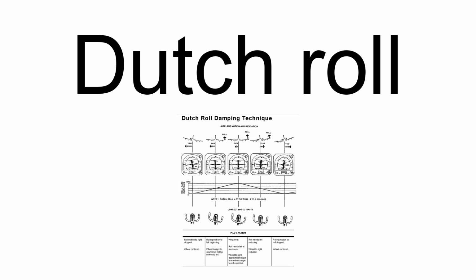Wings placed well above the center of gravity, sweepback (swept wings), and dihedral wings tend to increase the roll restoring force, and therefore increase the Dutch roll tendencies. This is why high-winged aircraft often are slightly anhedral, and transport category swept-wing aircraft are equipped with yaw dampers. A similar phenomenon can happen in a trailer pulled by a car.